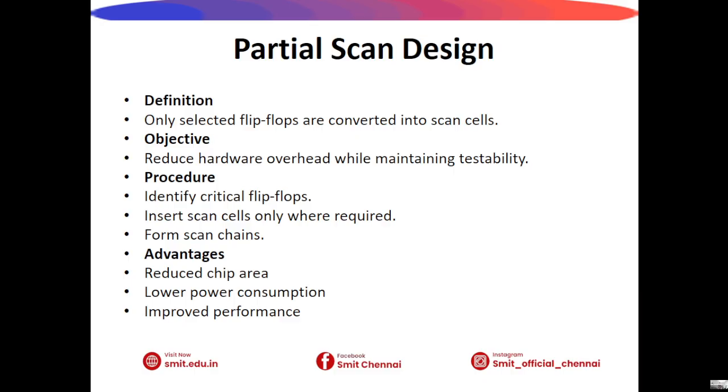Next, we see about the partial scan design. Full scan testing may require significant hardware overhead because every flip-flop is converted into a scan cell. Partial scan overcomes this limitation by selecting only important flip-flops for scanning. These flip-flops are usually chosen based on testability analysis. Partial scan reduces area overhead, power consumption, and performance degradation while still providing good fault coverage.